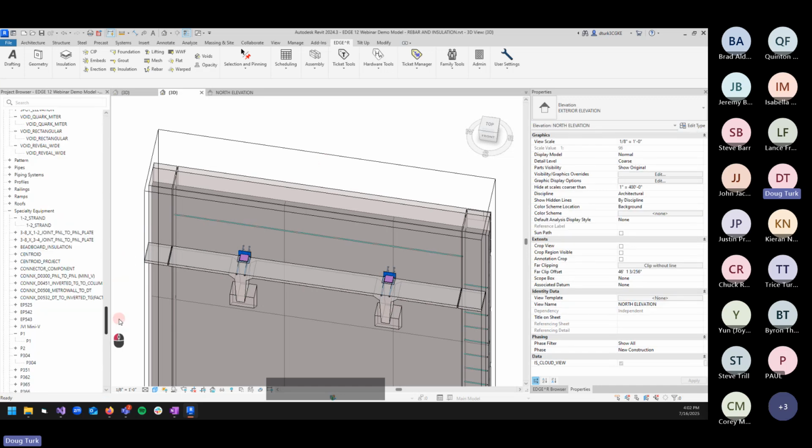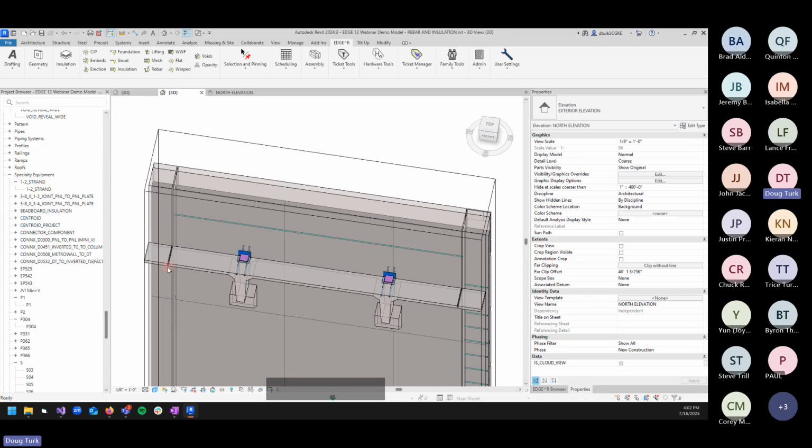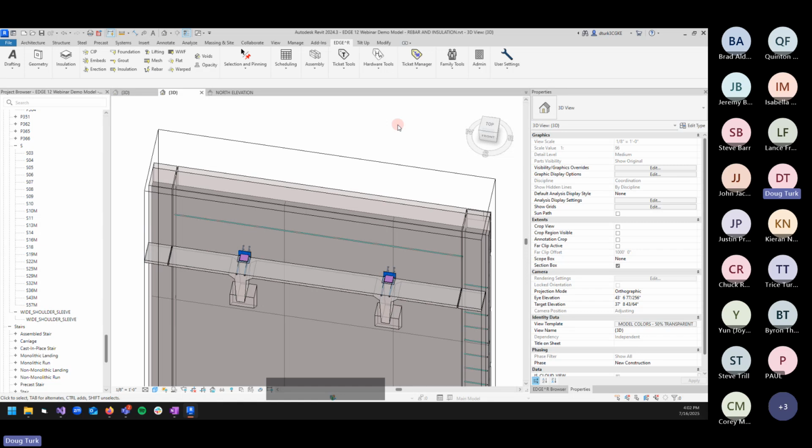We do also have bent bars. I think we've only shown straight bars, but rest assured we do have bent bars. I'm not going to bring them in right now because that would take some time, and I do see other questions coming in. For now, just understand that you place it bar by bar on the face that the reinforcement cover would be, and then bring it to exactly the location you want. Lengths and legs and such are handled with parameters.